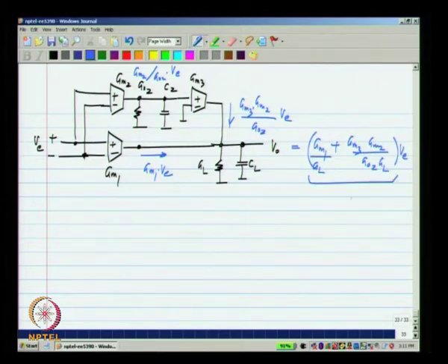And this is the DC gain. Now, it is very easy to see that this was the original DC gain and we have added this much to it, and in fact, what we have added is likely to be much more than the original DC gain, because it essentially is the DC gain of 2 stages. In fact, it is a similar number to what you got from the 2-stage Miller compensated op amp.